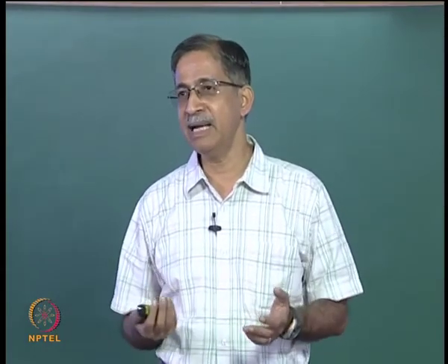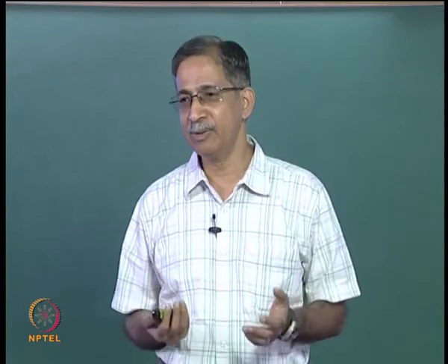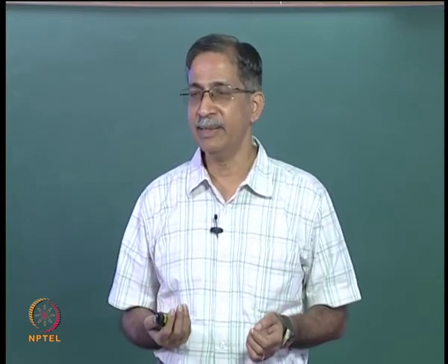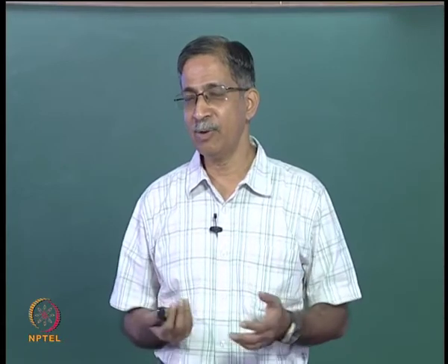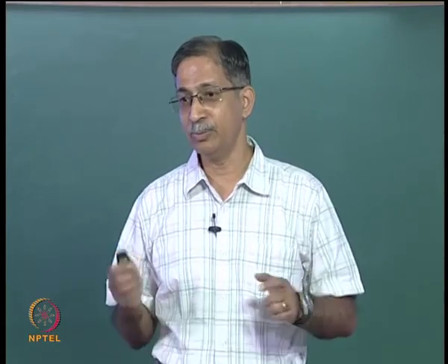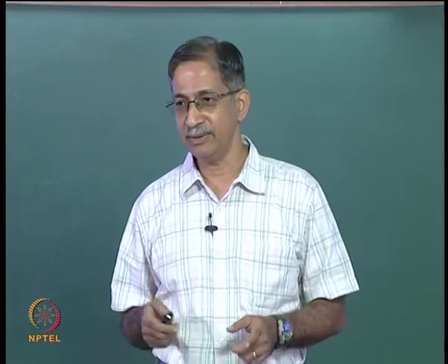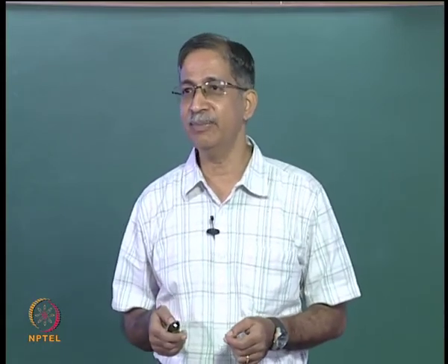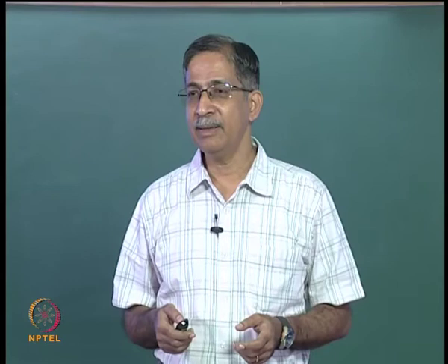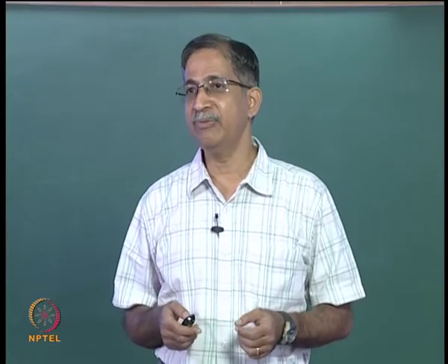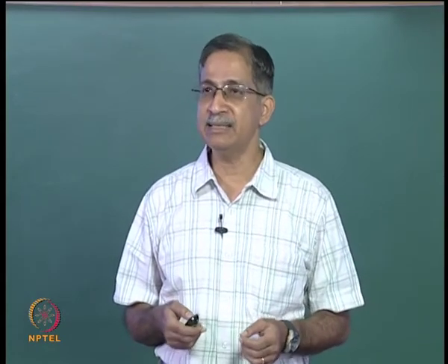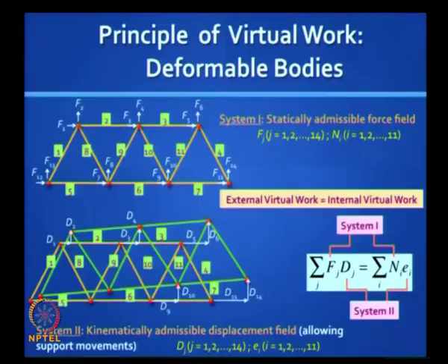There is some commonality between those numbers, but there is no cause effect relationship, and the sequence of loading and all do not come into this, which would come in an energy formulation. So that is the advantage of a virtual work formulation. Now if you take the internal field, the internal force is Ni in system 1 and corresponding Ei in system 2, and do a product and an algebraic sum, then you have the internal virtual work.